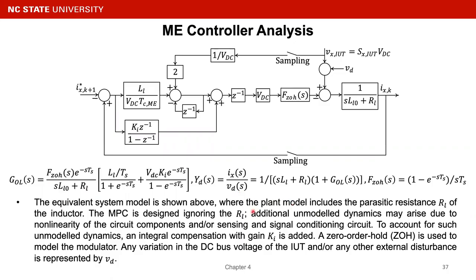It is worth noting that the plant model shown here includes the parasitic resistance of the inductor, while the MPC is designed ignoring this resistance. Additional unmodeled dynamics may arise due to the nonlinearity of the circuit components and the sensing and signal conditioning circuit.